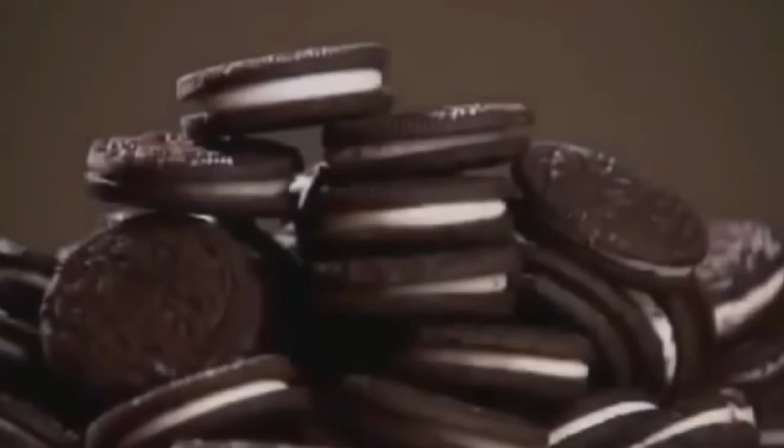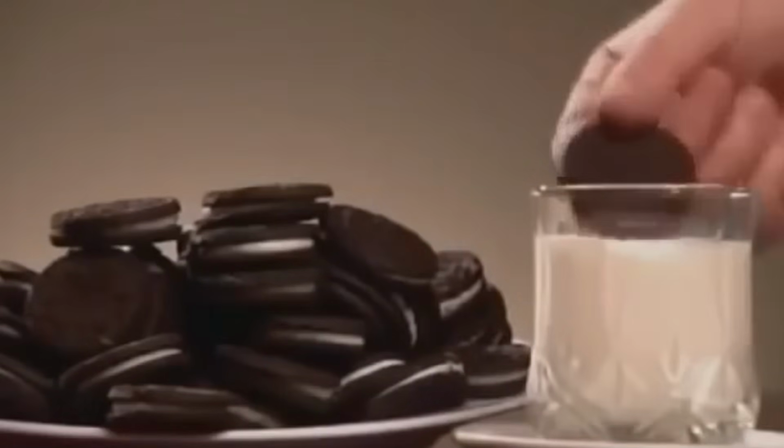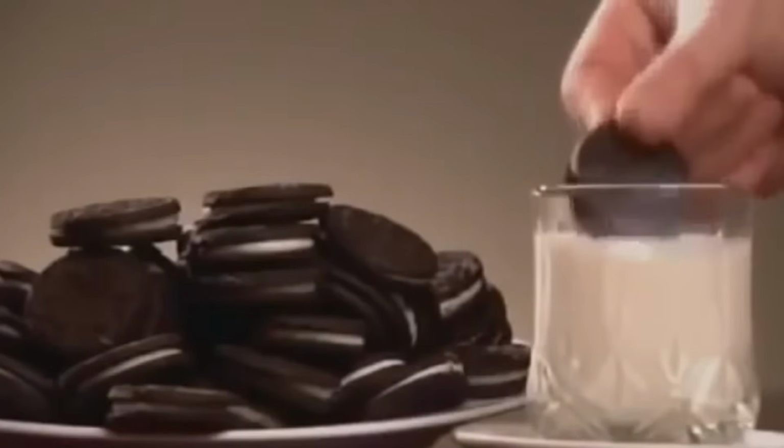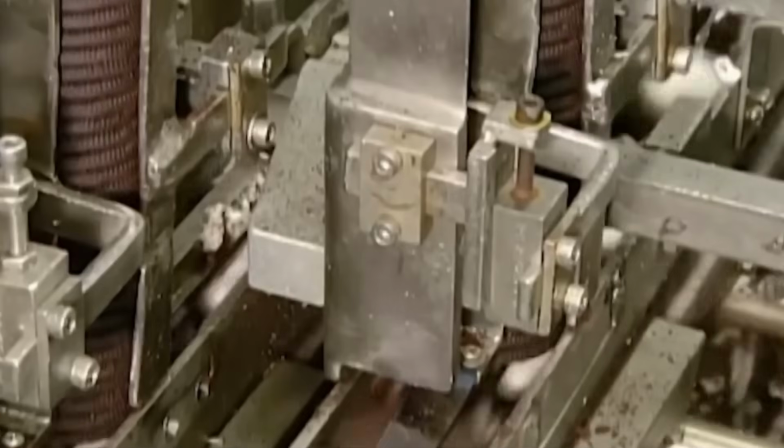Conveyor speed, airflow rate, and internal oven temperatures are continuously adjusted via programmable logic controllers that interface with sensors monitoring internal humidity, surface temperature, and even color of the baking cookies using infrared imaging systems. The target bake is one where the cookie becomes crisp and fully set while retaining a slight moisture gradient at its core, enough to ensure it sandwiches cleanly without shattering, and holds up in milk without becoming soggy too quickly.